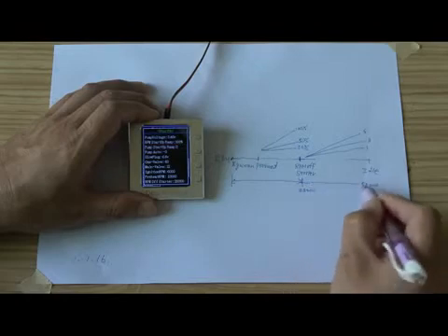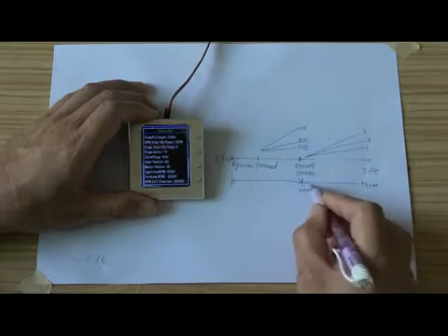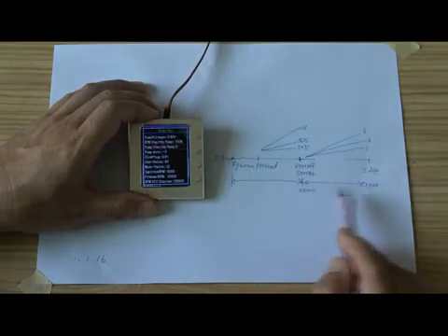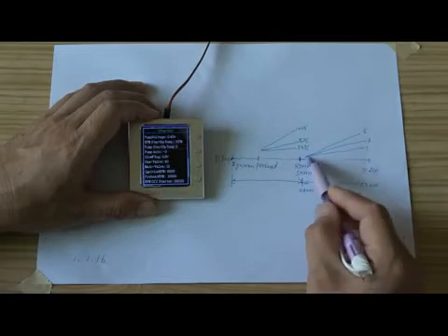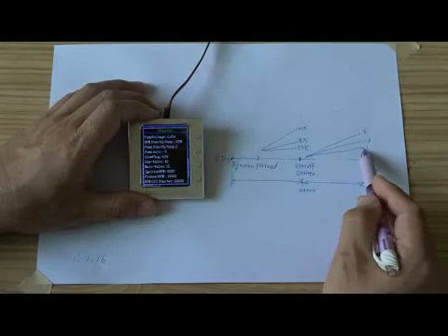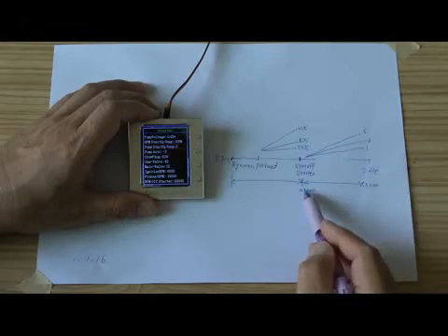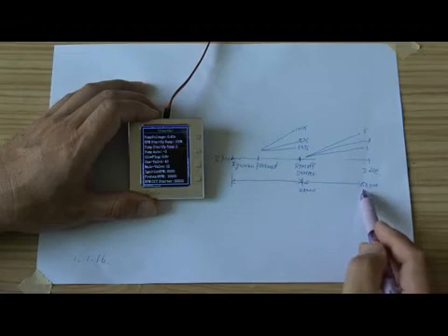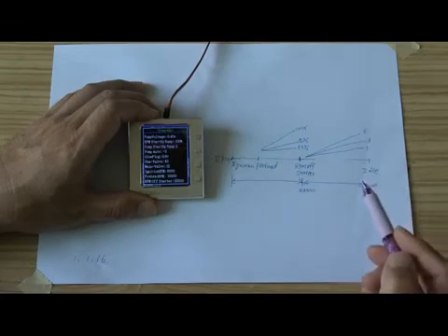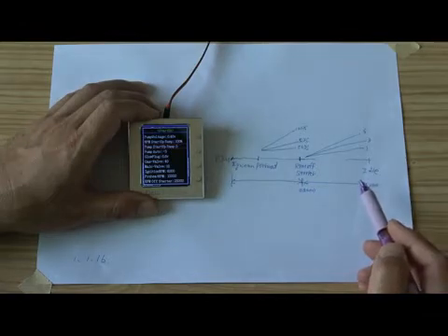The RPM will increase very quickly in this range, but will bring a little bit of fire. If you want it slow, the ramp is slow, and the turbine from 25,000 to idle RPM will increase very slowly. It looks stable, but takes a lot of time.